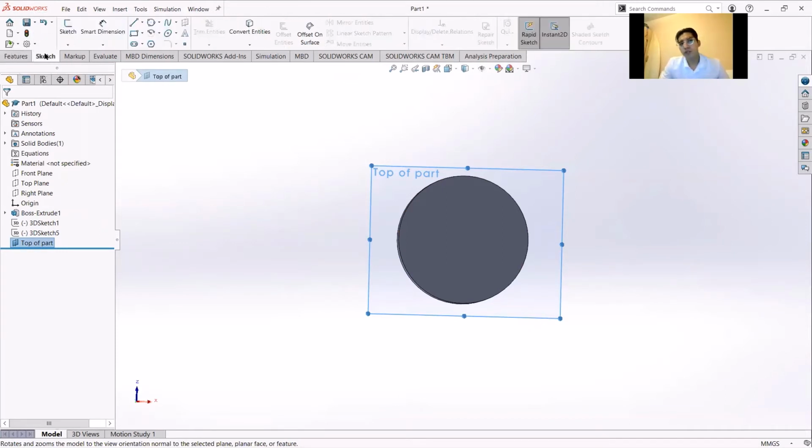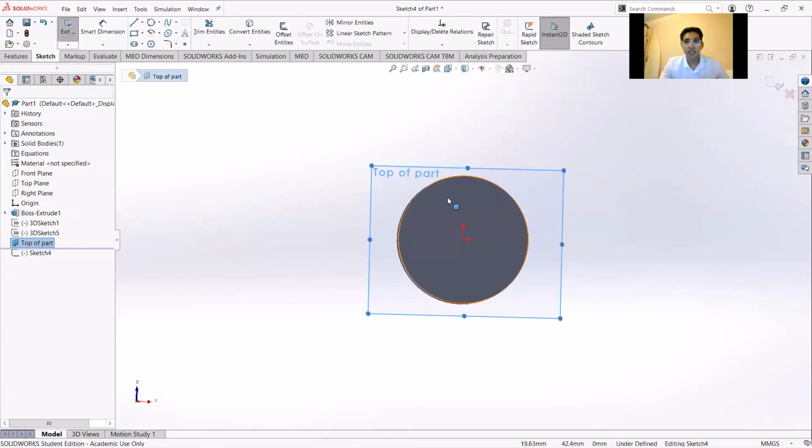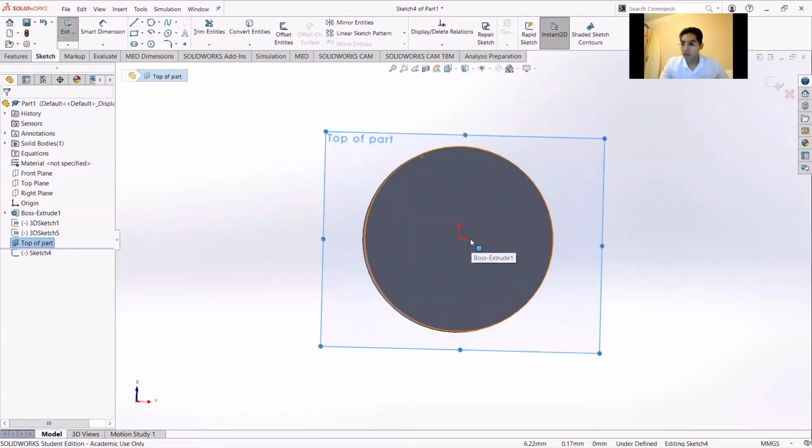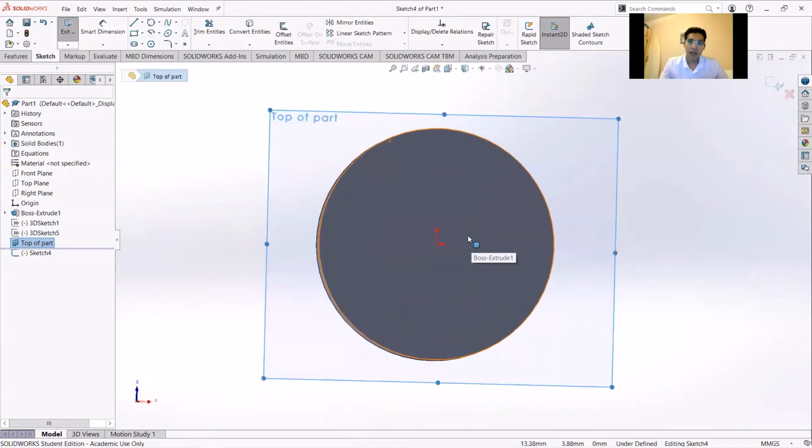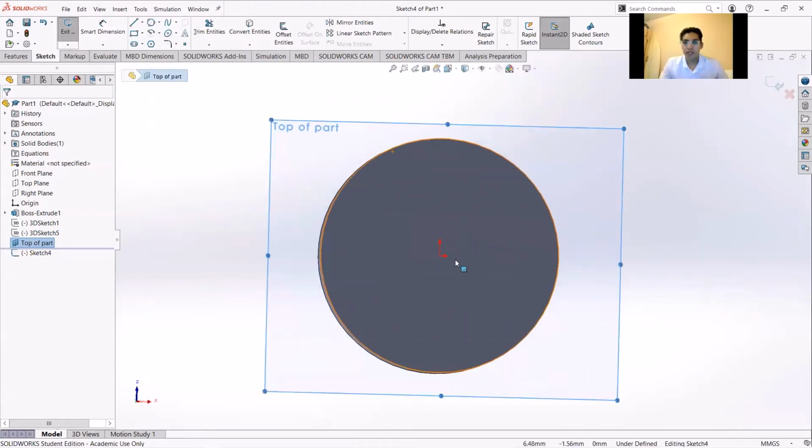Once you push Sketch, you're going to push the button over here, also called Sketch. This is basically creating another sketch on that plane. Once you've done that, you can zoom in and out with the scroll wheel forward or back. It's nice to keep it kind of close or centered.